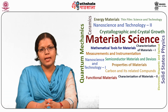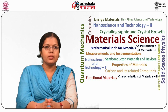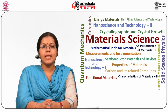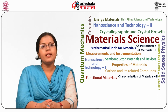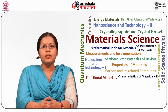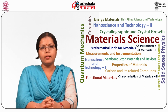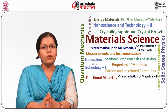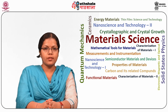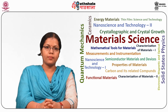This system has the advantage that all multipliers except the first have standard resistance values and can be obtained commercially in precision tolerances. The range multiplier R1 is the only special resistor which must be manufactured to meet specific circuit requirements.